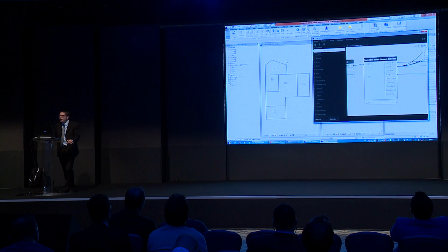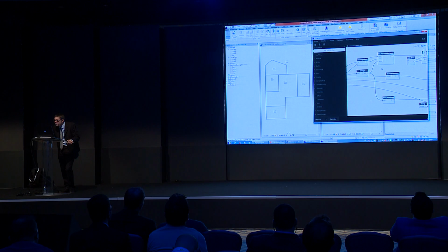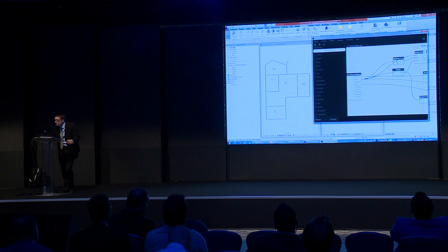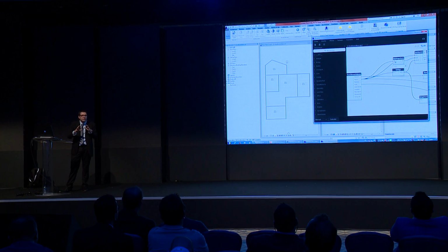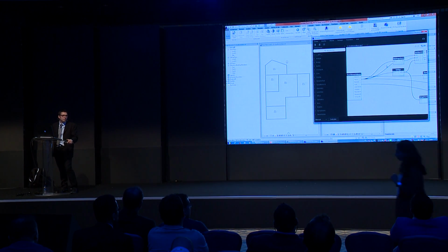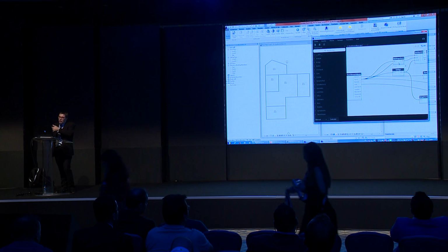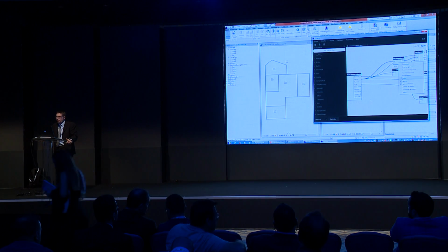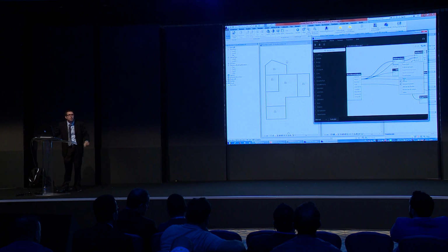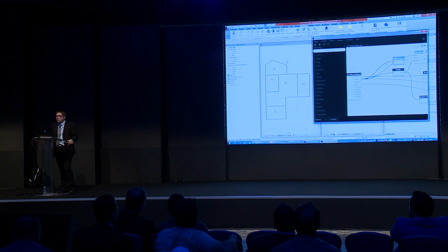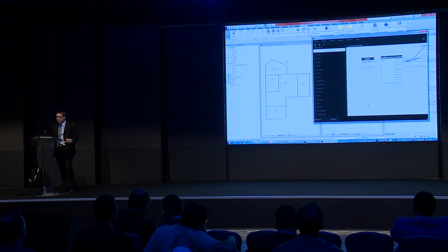Let's avoid some of this. I will remove this. Another trick in Dynamo: you can freeze a node, rather than disconnect it as I do. I don't do it now, but you can. Sorry, it's a French interface, but freeze. That means if there is some information in this node, it does nothing afterwards. If I run this script,